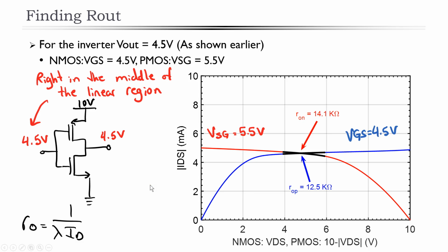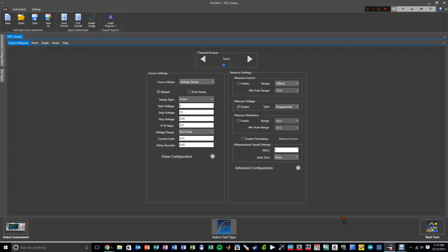Now one other thing I want to point out is the reason we call this a small signal parameter is that the slope is only really accurate in that small region. If I start to go further and further away from that operating point, we can see that obviously it can no longer be approximated by a straight line. So that's why we use the word small signal, right? The input needs to be within some range for it to be able to be approximated with a straight line. Right, and if you go beyond that range, then the device becomes nonlinear, and that's a whole different discussion on analyzing the large signal behavior. But for now, we're focusing only on the small signal.